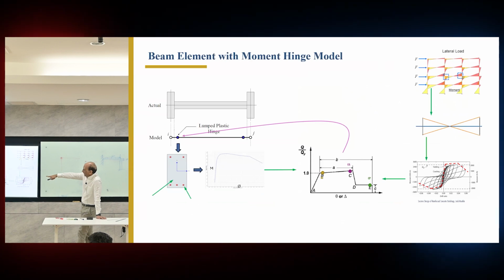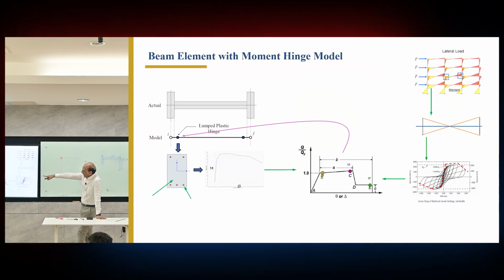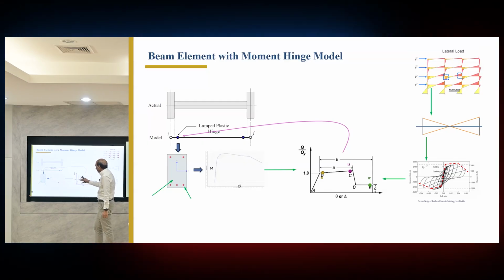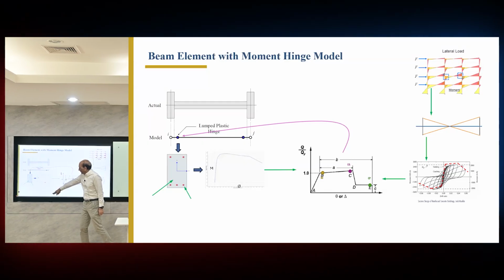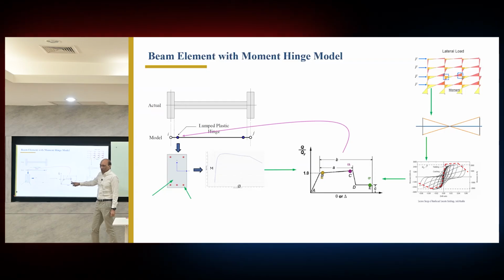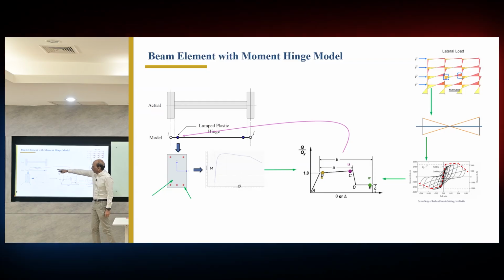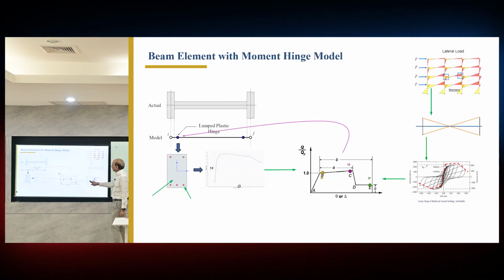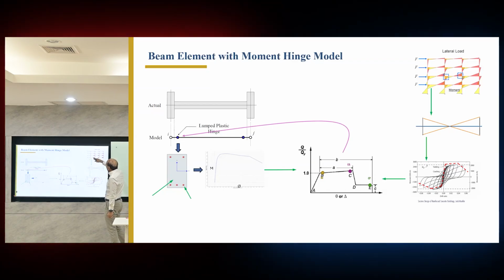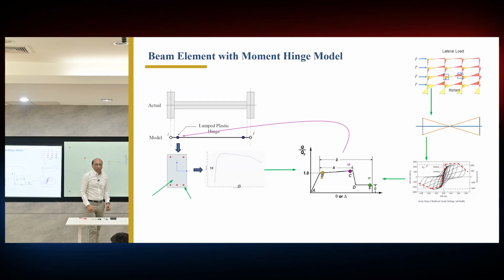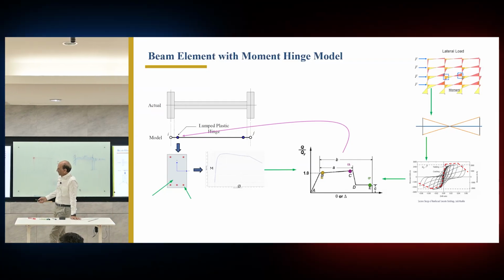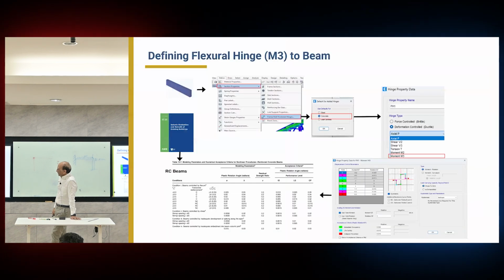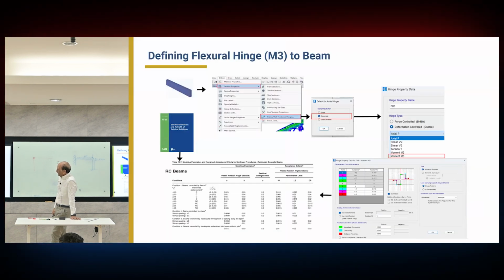And then this was the way to do that. You put the hinge there, and from there you define the cross section. Then the moment curvature curve for that will give you that this is the real moment curvature curve. This is the idealized moment curvature curve. And then you put that back into the hinge and then add the plasticity model onto that one, the damage model onto that, and then you have the analysis from there. So that's the way that you can just put a simple hinge there and do the analysis. More details about that and how to define that.